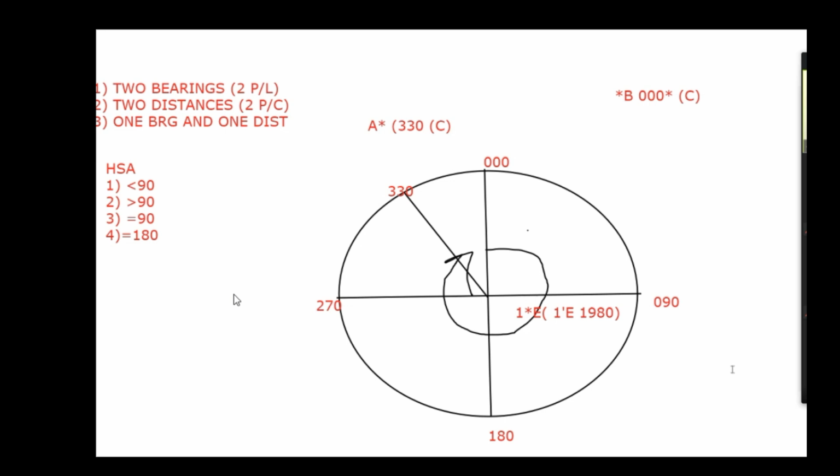So they correct it. Still, the deviation depends on the vessel and the course. If the course changes, your deviation also changes. So deviation depends on course. I'm not talking about the bearing. The three bearings I'm giving are not the course. Deviation depends on course, not on the bearing. So on a particular course, whatever the bearing you get, the deviation you get, and the variation you get from the chart, the compass error for a particular heading is constant.